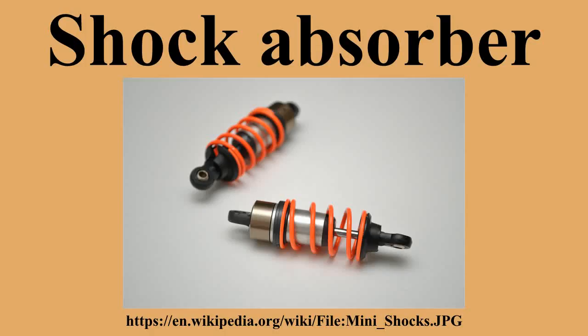Realizing that the spring and vehicle combination bounced with a characteristic frequency, these auxiliary springs were designed with a different period, but were not a solution to the problem that the spring rebound after striking a bump could throw you out of your seat. What was called for was damping that operated on the rebound. Although C.L. Horrock came up with a design that had hydraulic damping in one direction only in 1901, it does not seem to have gone into production right away.